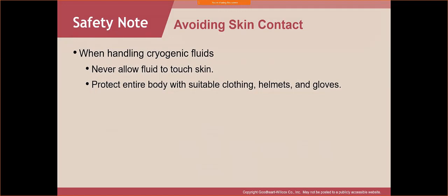So when handling cryogenic fluids, never allow fluid to touch the skin. One of them would be liquid nitrogen. Everybody's heard of liquid nitrogen. Maybe you've even seen demonstrations where somebody takes a rose, dips it in, pulls it out, and all of a sudden they're able to crack or smash the rose into millions of pieces because it's basically turned the rose into a fragile ice block.